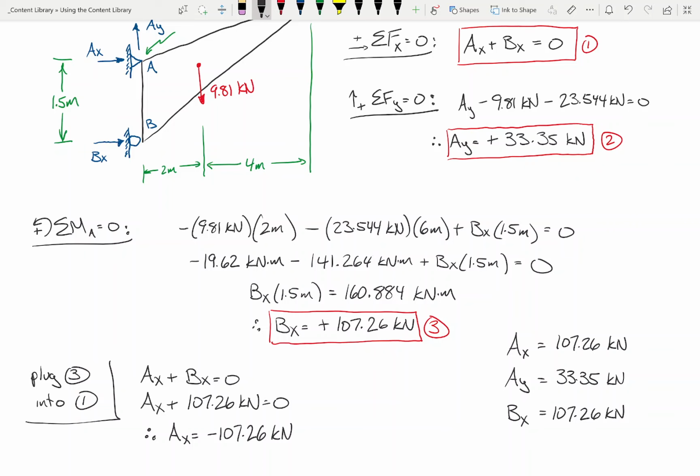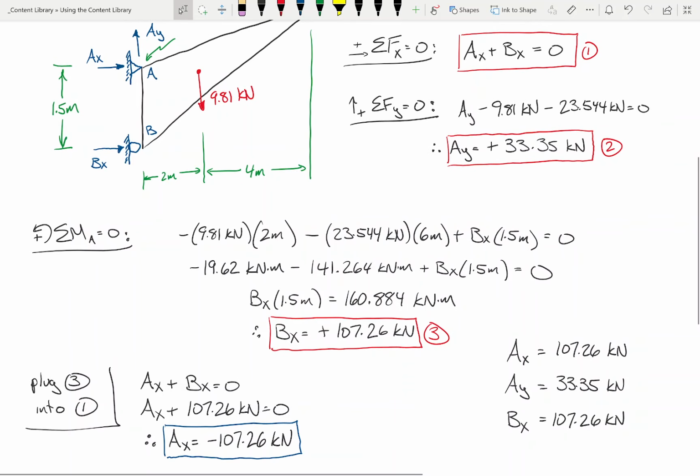So again, the positives or negatives that we have in these equations here, and for example in this box here, the reason that these values come out positive or negative is because they map to the sign convention that we've used up here. This sign convention is based off of assumptions. We assumed AY, we assumed AX, assumed BX, we assumed those directions. So the answers being positive or negative are just a function of those assumptions. Really, what is true for everybody when they do the problem correctly is the magnitudes and the actual direction.